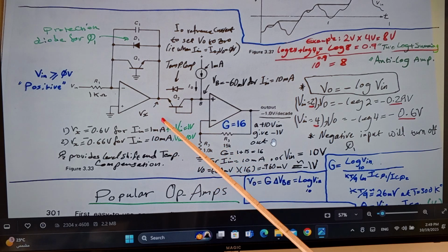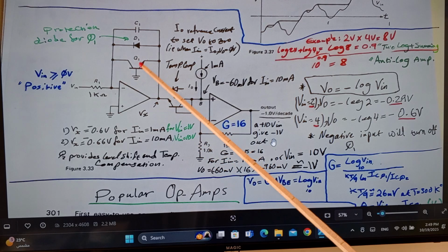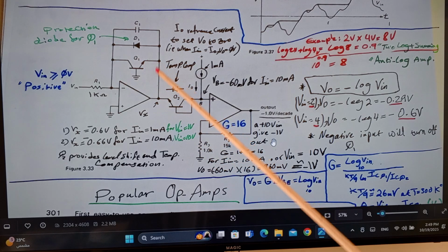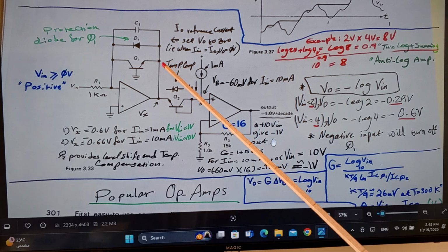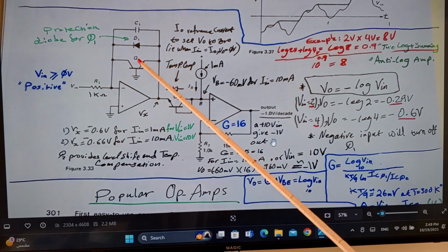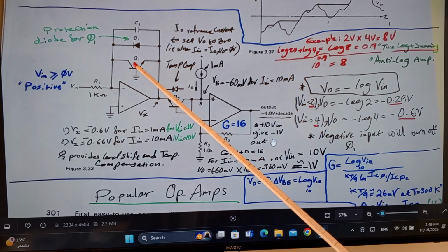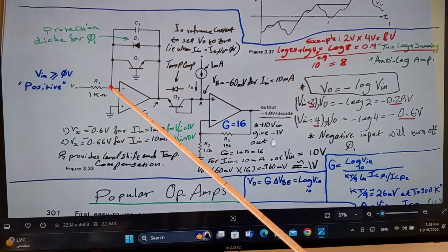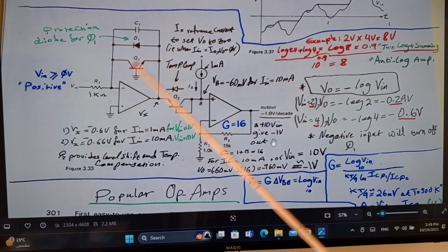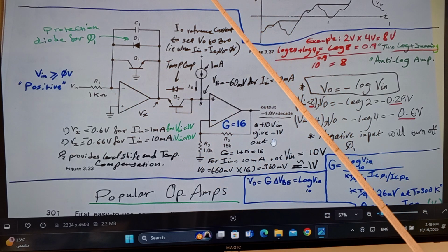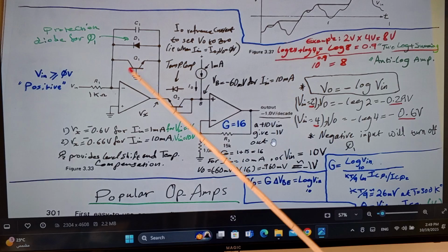And when it lowers its output voltage, it's going to turn Q1 on. And a current will start flowing through that transistor from the emitter all the way to the collector in there, and through the op-amp and that transistor, and then you're going to create your virtual ground in here. And this is a closed loop, by the way. This is a feedback. That's a closed loop.